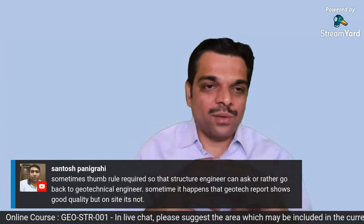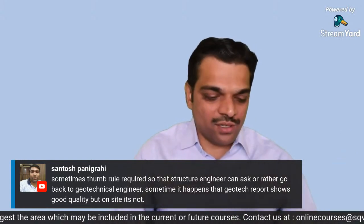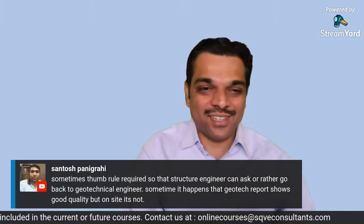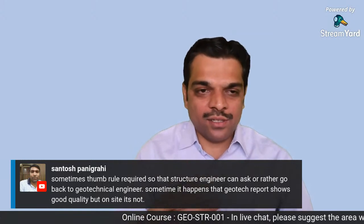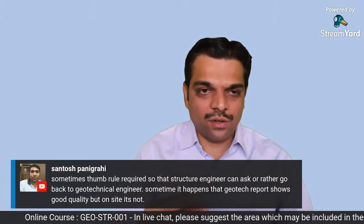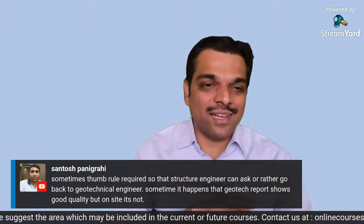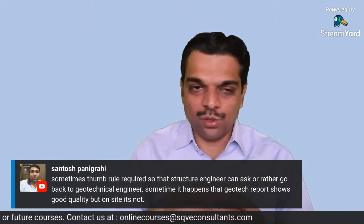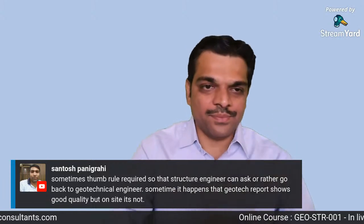And there was a very big impact on the project, a lot of reconciliation, a lot of recalculation, because one foundation was sitting on a very deep foundation, and another foundation was sitting on a shallow foundation. So what I mean to say is that there could be a lot of variation even after doing the geotechnical investigation. That's why I personally prefer a joint visit of the geotechnical and structural engineer to the site after excavating the soil up to foundation level, and then we should ascertain that whatever kind of soil we have considered as part of the geotechnical investigation report or the foundation design is there on the site. So your point is very valid.